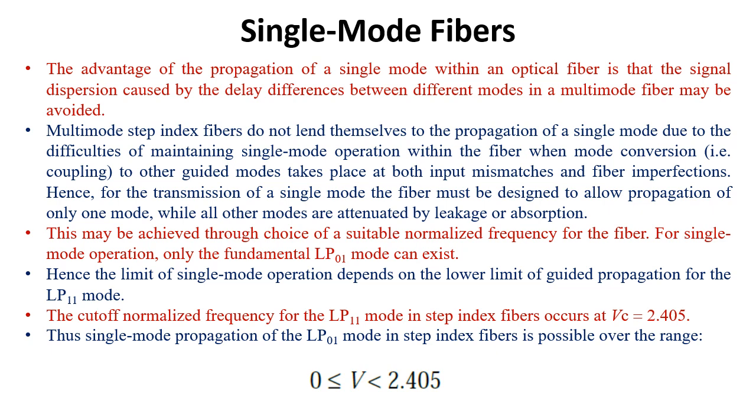The advantage of propagation of a single mode within an optical fiber is that the signal dispersion caused by the delay differences between different modes in a multimode fiber may be avoided. Now, multimode step index fibers do not lend themselves to the propagation of a single mode due to the difficulties of maintaining single mode operation within the fiber when mode conversion, that is the coupling of modes to other guided modes, takes place at both input mismatch and fiber imperfections.